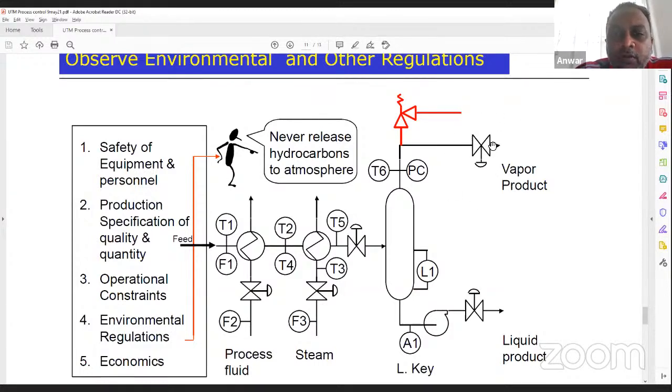So it was very crucial that the plant have good control on the chlorine system, where we have multiple detectors around the system to trigger us if there is any slight leakage, even lower than 0.5 ppm. We can detect it and ensure that it is attended to accordingly, and continue the safe operation.